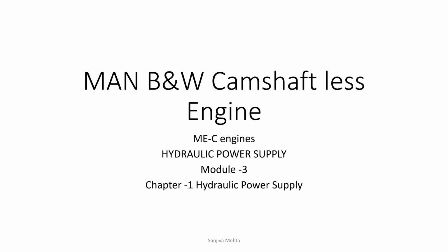Here, module 3, we will discuss hydraulic power supply. Hydraulic power supply, because the actuation of the FIVA, exhaust valve, and cylinder lubrication is all carried out by hydraulic pressure, not by mechanical force as in the conventional engine, because there is no cam, no camshaft, no drive shaft, nothing. So naturally, hydraulic pressure is used.